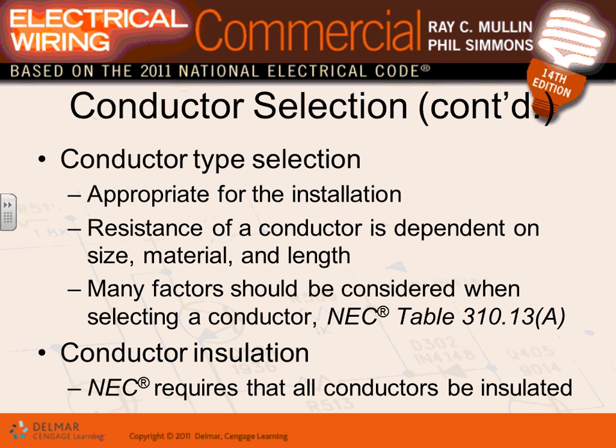When you select a conductor, and some of this stuff, guys, is a review for you, the first thing you select is the insulation. If you're doing conductors inside the building, your insulation is going to be THHN, right? If you're selecting conductors for outside, your conductors will be THW. Done. So the insulation. Also the size will determine the resistivity, and that also determines the voltage drop. So when we size them, we have to take into consideration voltage drop.